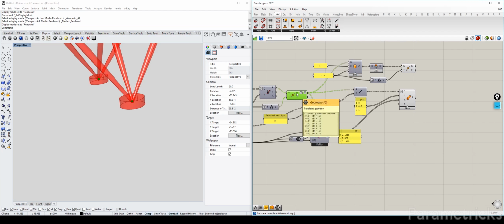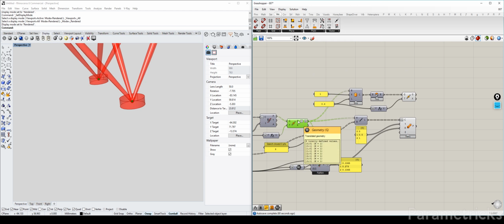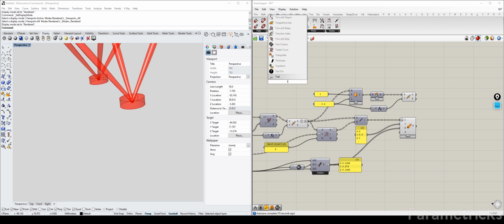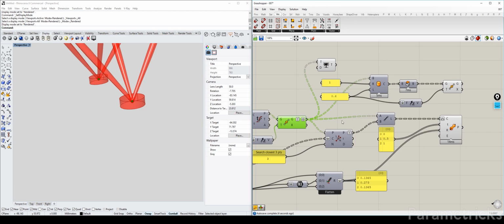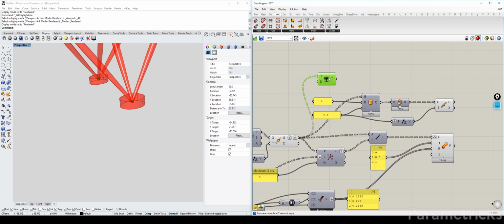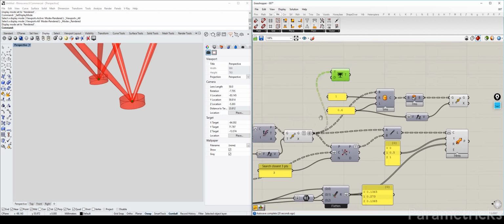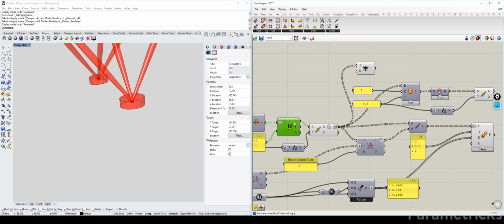The points I need are these. How am I going to get the vectors out of these points, actually? I might need to regroup them back. So let's trim the tree. You can actually remove the graph here, but the graph is used by so many things that it's just better to just trim the tree down. And what the trim tree does is actually it takes your path. As you can see, we have 2 levels of branches. It will try to eliminate the outer 1 branch because we set it to 1, and will give us back sort of when we before we even move it.